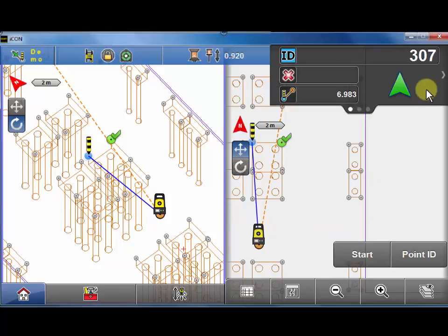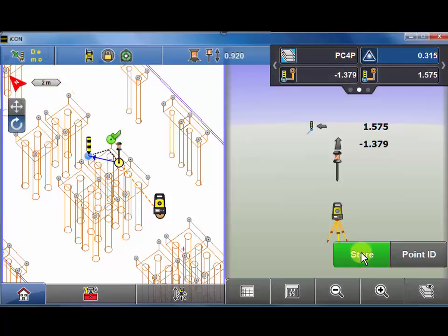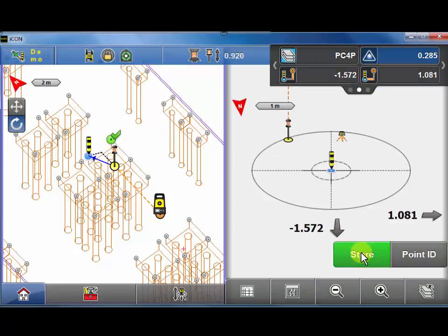Once the point is selected and the measurement is triggered, the distance to the target is replaced with the distance between the station and the current position of the pole. Arrows and corresponding distances are displayed to indicate how to find the point to be staked out. Arrow view will change to bullseye view if the target is within 2 meters distance to the selected point.